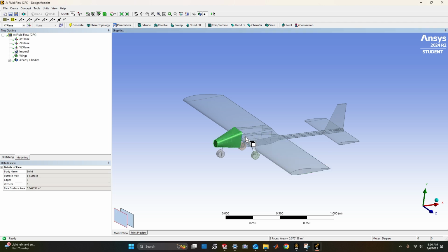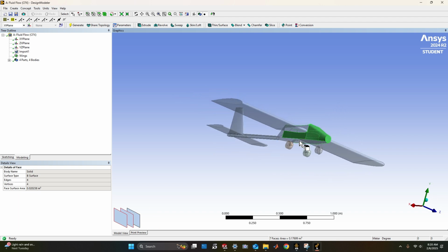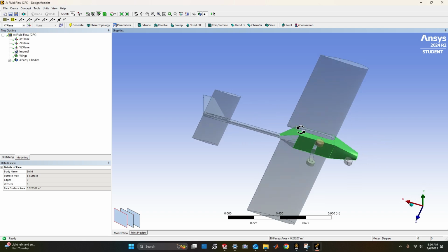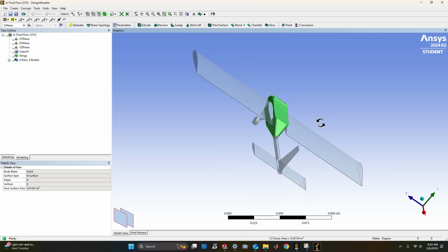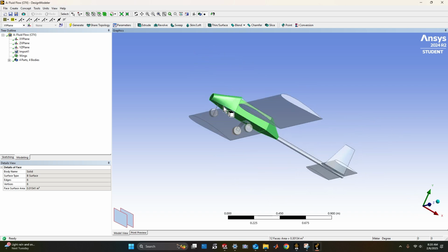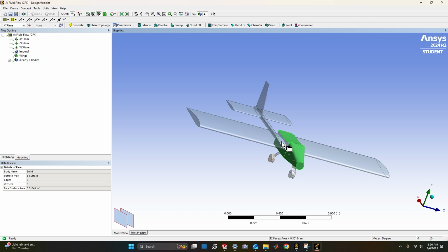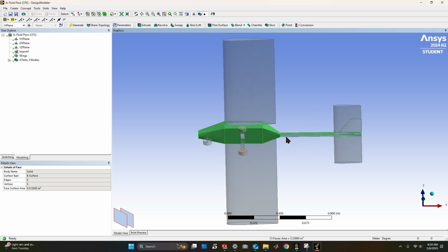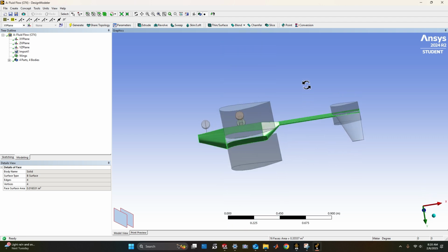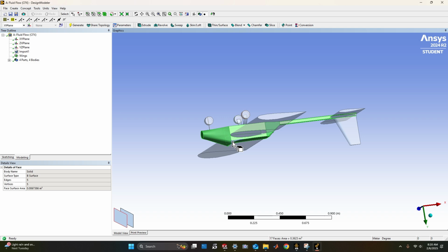So I'm next starting on the fuselage. So selecting all the various parts of that, all around it. This one tends to have the most faces and will count as a significant portion of the drag. This front part here might instead be characterized as part of the motor drag, but I'm going to include it in the fuselage for this, since I can just edit the math later.